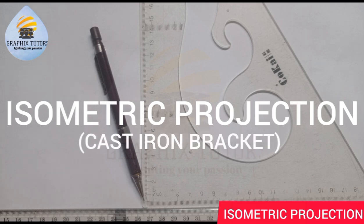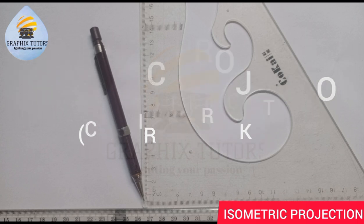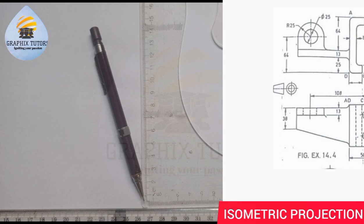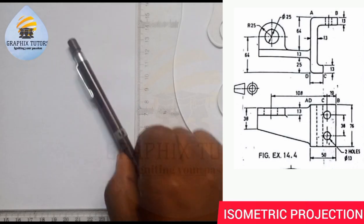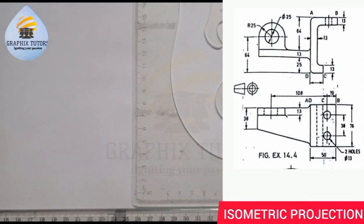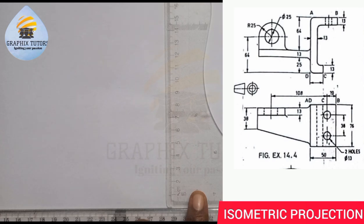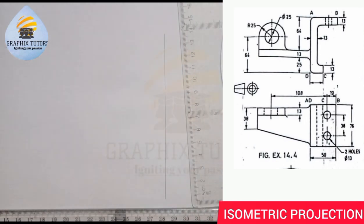In this video, we want to reproduce the orthographic view that is displayed at the right hand side of the screen in isometric projection. Now when you hear the word isometric projection, the first thing you should do is draw your isometric axis, right? You draw your vertical axis this way, right?